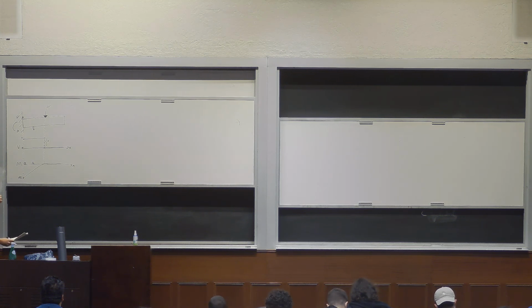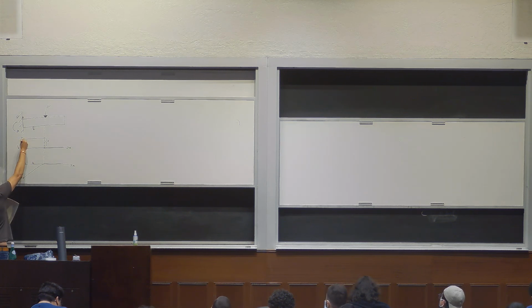And the reason I show this is because for these types of problems that we're talking about right now, you would normally have to do this process of finding V and M given the loading situation, and then you would use M and V at any given location. For example, in this problem, we would care about the base of the structure because this is where both the shear and the moment are at their highest magnitude, okay?